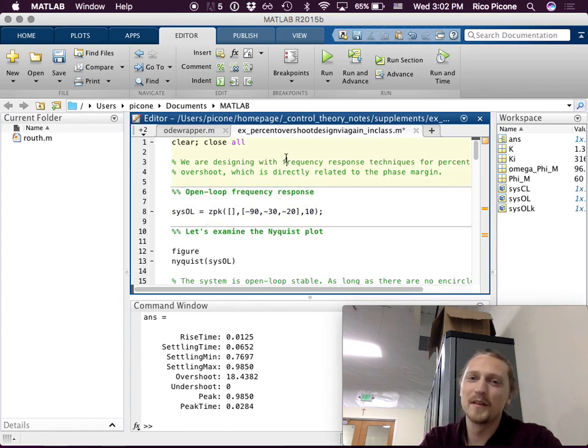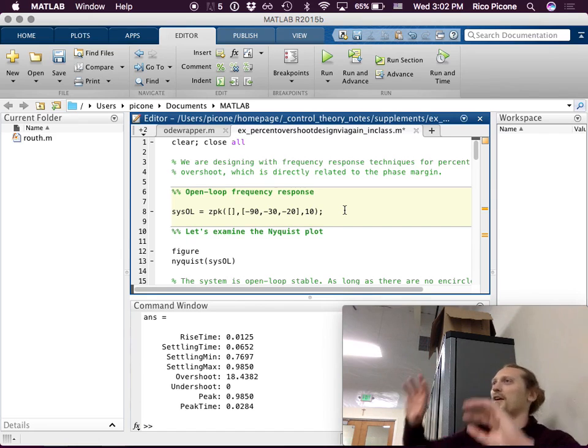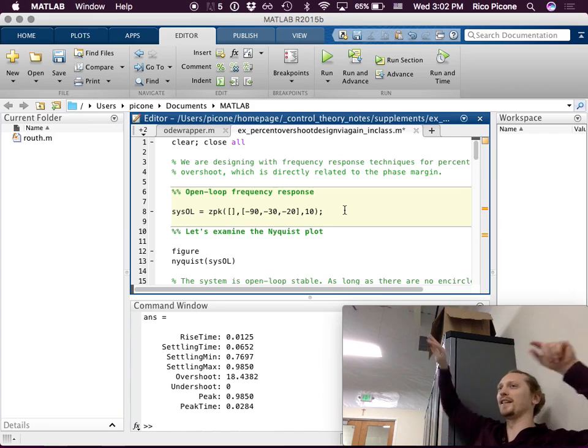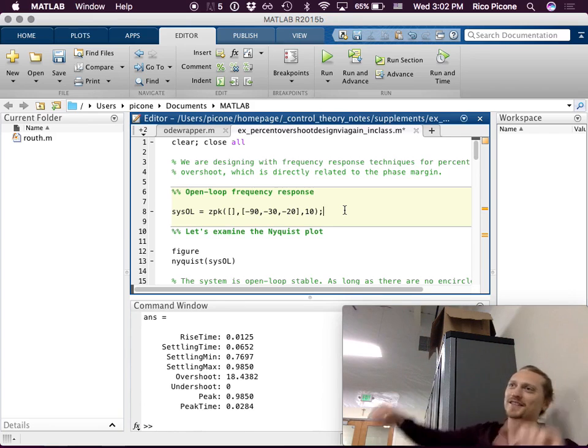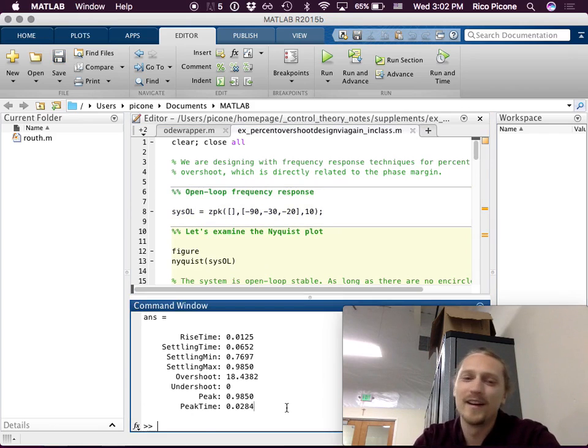Yeah, so let's do it with another pole on the real axis. So I believe that for this system there's going to be a gain where the locus goes off like a sideways peace sign, and at a high enough gain, it's going to cross the j omega axis. That's how I feel. We could do just for fun a root locus of the open-loop system.